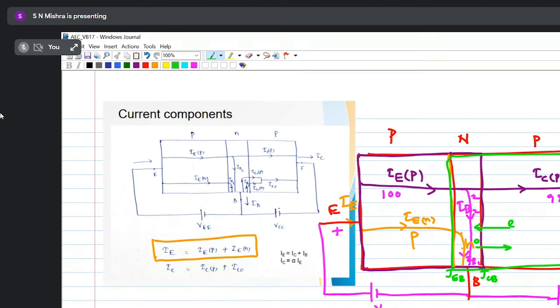So due to that, we'll get some current. So electron is moving from collector to base. So what is the direction of current? Base to collector. So you see here, this one is your ICO due to electron. I have written here ICO due to electron. Similarly, hole is moving from base to collector, so the direction is base to collector. So the upper one is ICOP. You see here ICOP, ICON.